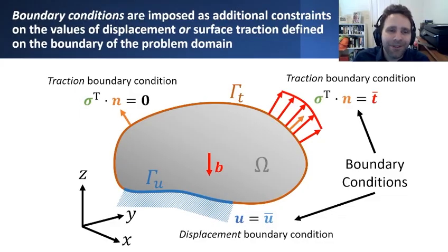But that still qualifies as a particular case of a traction boundary condition for which that prescribed traction is simply the zero vector. So it's important to be specific in including zero traction boundary conditions as nonetheless qualifying traction boundary conditions that we have to prescribe on the boundary.